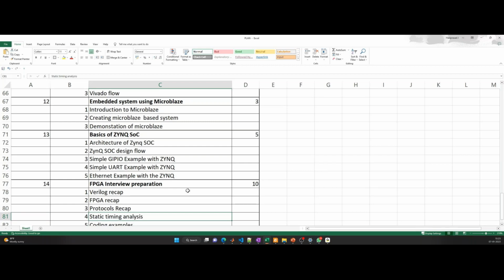When I say FPGA, if I say 10 kilo logic gates are there in the FPGA, you have to write the RTL in such a way that it will fit within 10 kilo. If it is not fitting within 10 kilo, then you have to go to another FPGA itself. There is no other option, right? You cannot push and make the entire thing fit. You have to optimize the algorithm, or you have to change the FPGA itself. That's the objective. But in ASIC, it's not like that.